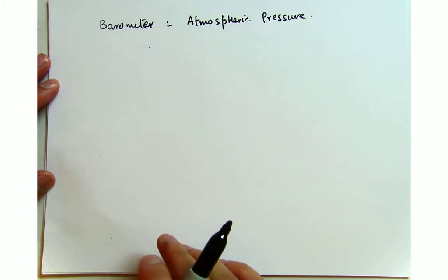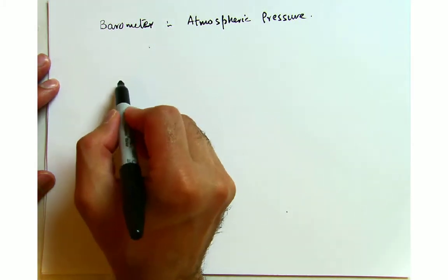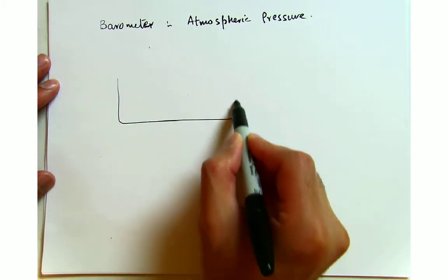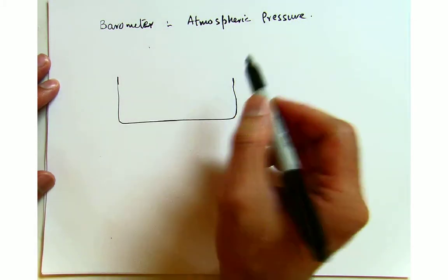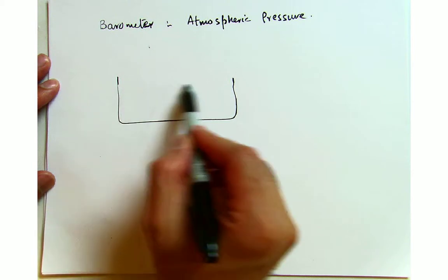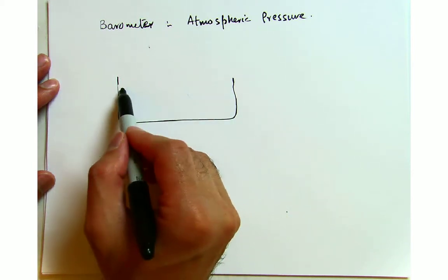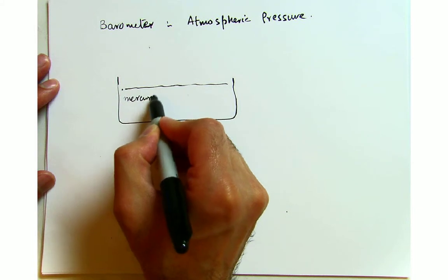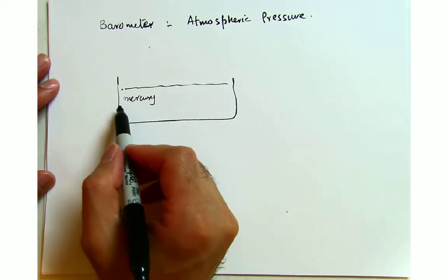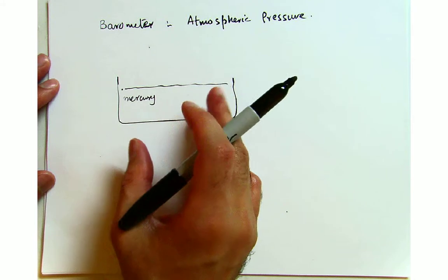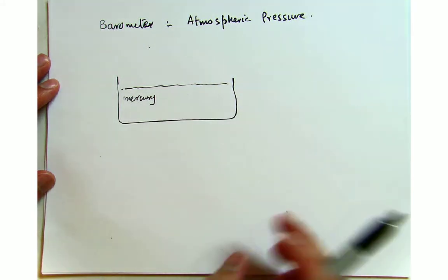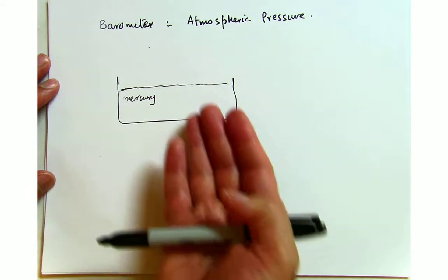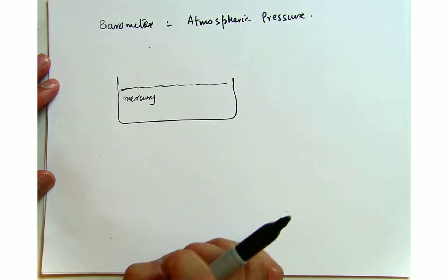Okay, so we can measure the atmospheric pressure, and the way this goes is, let's suppose we take some container filled with a liquid. In this case it could be any liquid, but I'm choosing mercury. The only reason I'm choosing mercury is because mercury has a very high specific weight, and it also has a very low vapor pressure. Because it's a very heavy fluid, it's not going to lift up as much, and I will just mention that about water.